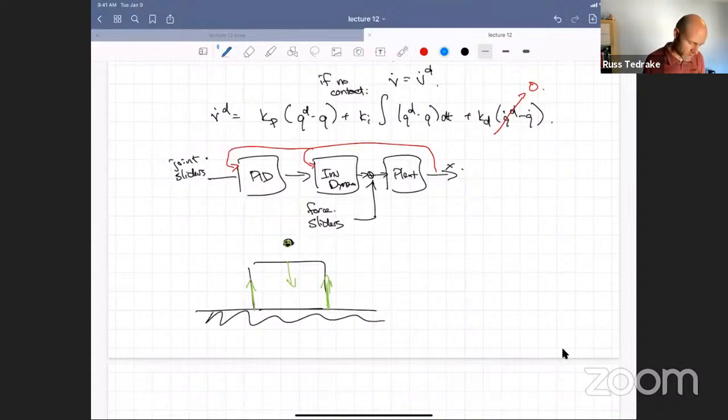So let's just make sure. I think the thing that's potentially confusing about that is that we have multiple force vectors. We're representing our contact with the table with, right now in my picture two, you saw in the simulation four, really it's a pressure distribution if they had a real box, right? Does that matter? Does it matter that I got four vectors versus two vectors? Forces add. They enter the equations linearly, and the coefficients of friction are linear constraints on those forces. So it actually doesn't matter.